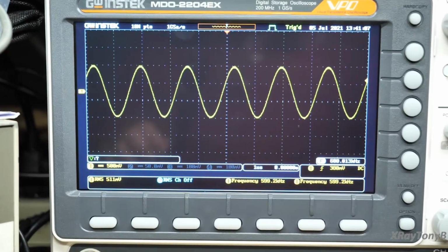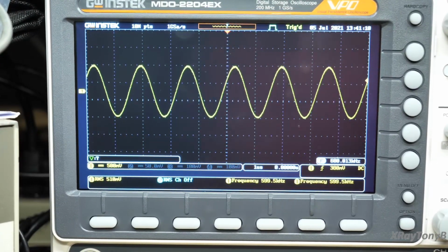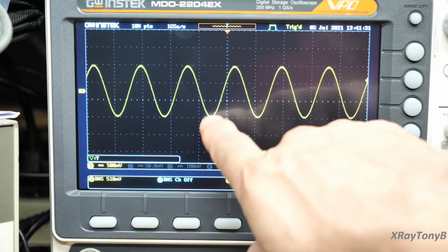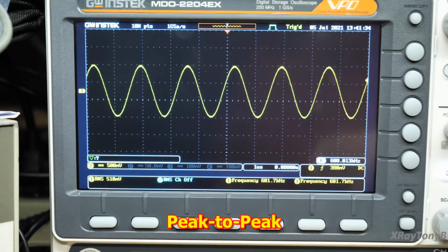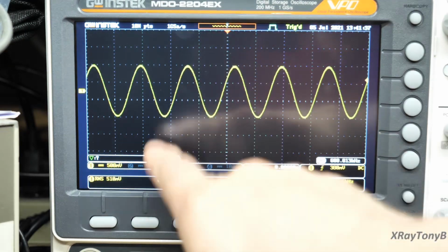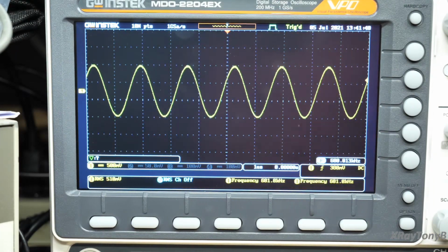Anybody? Well, we get into that in some other videos. If you look at my video on connecting a 50 ohm terminated test equipment to a non-50 ohm device, I get into some of this stuff. Remember, this is reading the peak value, not the RMS, which is what we selected, and this is not terminated properly with respect to the signal generator. So that's more than we need to get into in this video. But that is what we call a carrier signal right there.